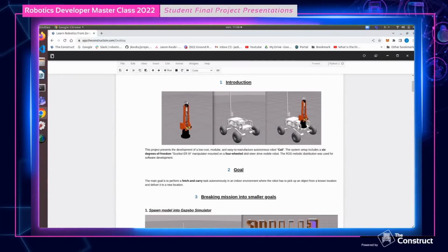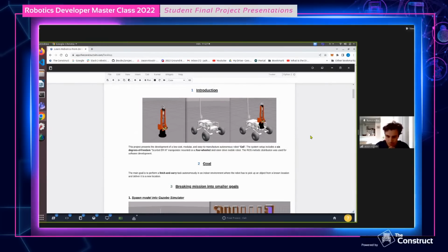But no, in Gazebo it won't work. So that trick that you did is a common trick. Or maybe another graspable object, more rectangular, instead of a Coke can, like a prism. Yeah, it will allow a better grasping, maybe. But it's what you mentioned, that in Gazebo the frictions are not properly handled. Yes, the physics of the friction.